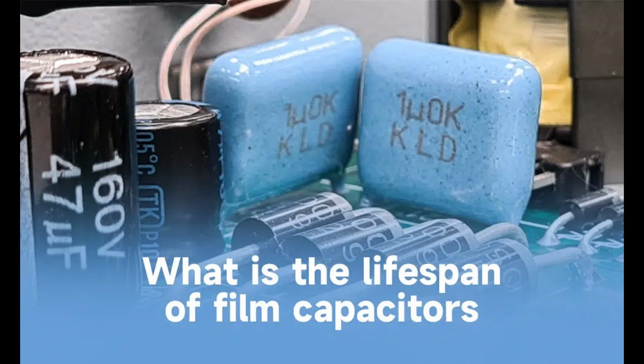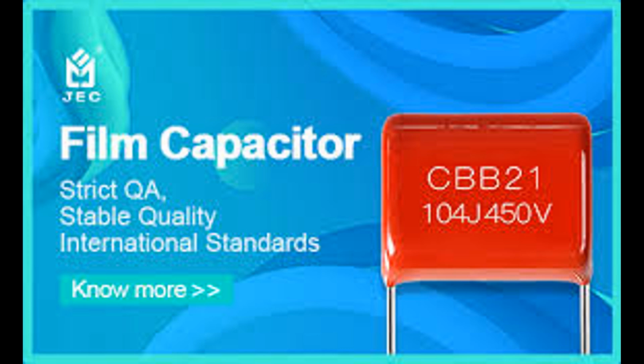4. Limited capacitance range. Lower capacitance. Film capacitors are not well suited for very high capacitance applications. While they can go up to a few microfarads, μF, they are not practical for applications requiring capacitances in the millifarad, mF, range or higher, where electrolytic capacitors are more appropriate. This limitation restricts their use in applications like large energy storage systems or bulk filtering.